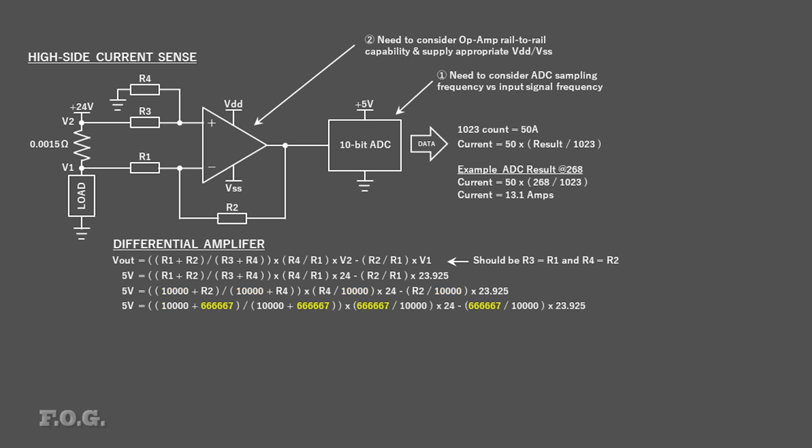And this is what we get, a 666,667 ohm resistor value. No, actually, I was too lazy to work out the proper algebra or walk you through it here. Instead, I simply used the goal-seek function in Excel and it spat out this value. I say work smarter, not harder. So let's test these values a bit and make sure it's all working as we would expect.